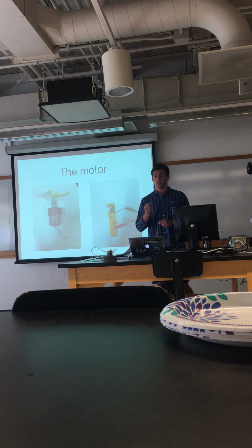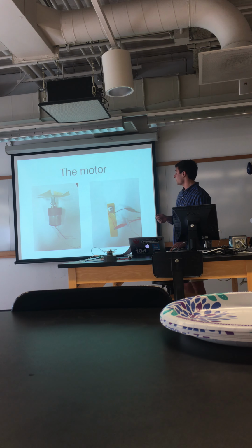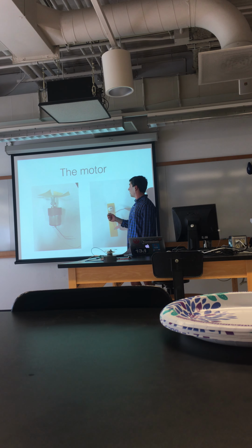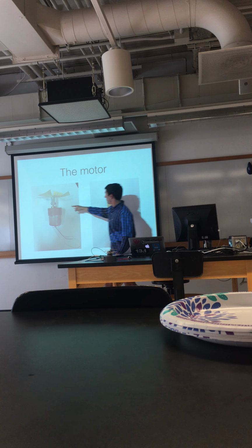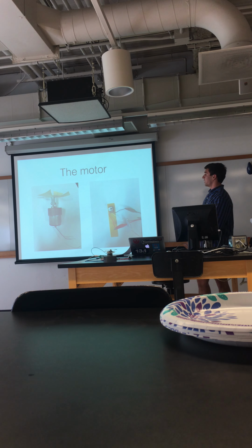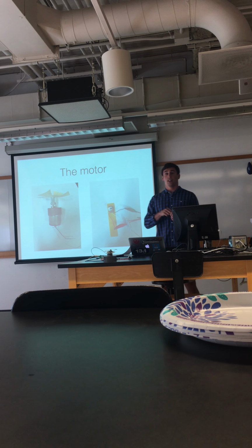Because the motor's axle goes up through the board, if I ever had to take the board apart, I have to take the fan off. How I accomplished that, with the help of Vic, was I got a spacer nut, which is this bit here. That spacer nut is a 1/4 inch, so it fits onto the axle of the motor, which actually already had a hole in it.